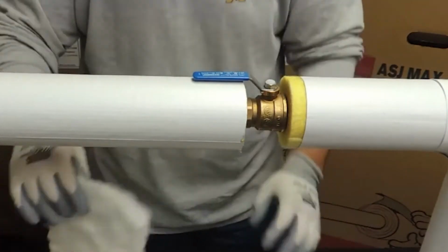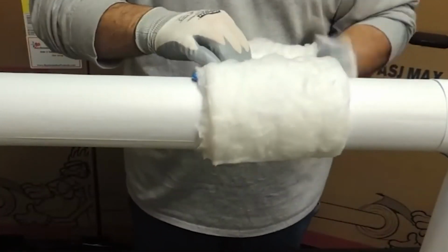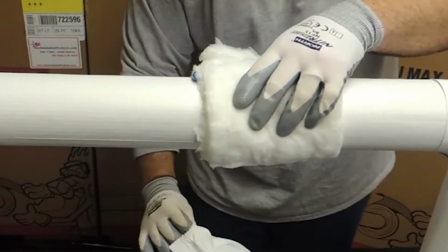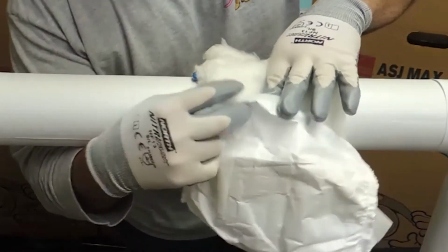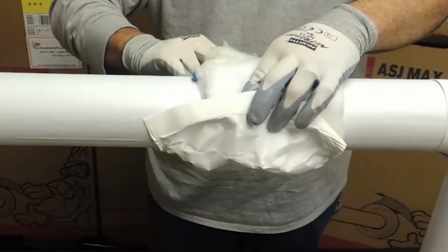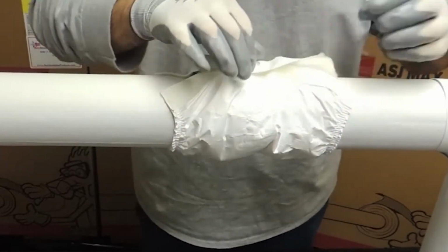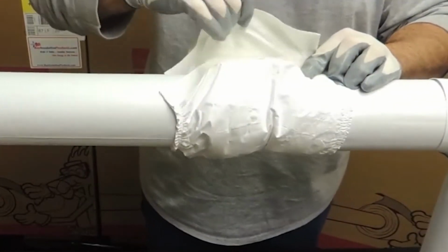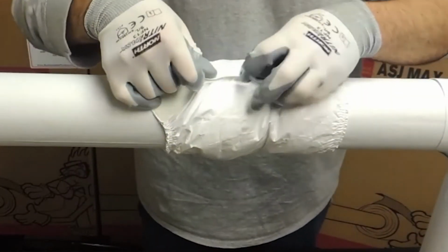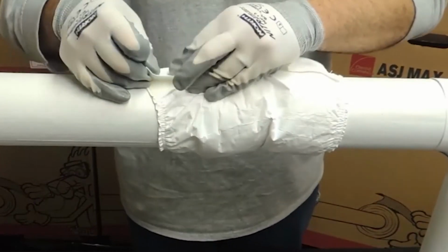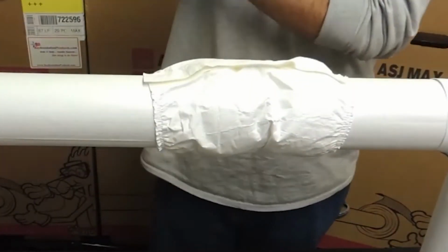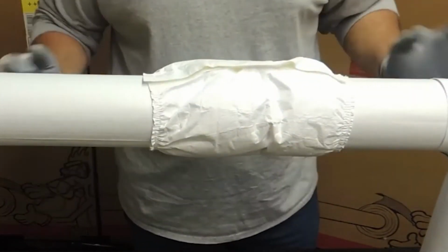The problem is usually not long runs of pipes. They're often well insulated, but the joints and valves at the end of these long runs are often left uninsulated. And this is something to pay attention to if you're doing a chilled water assessment. Removable Velcro type insulating covers are cheap and sized for all kinds of elbows, joints, and valves.